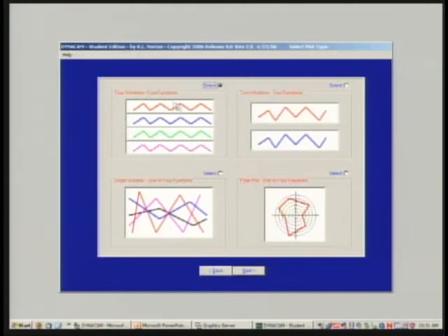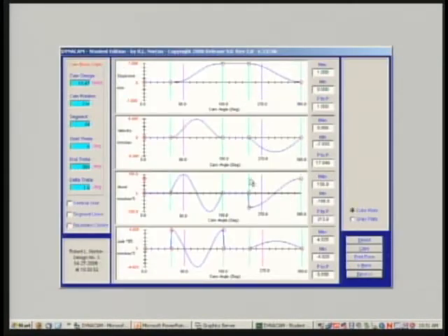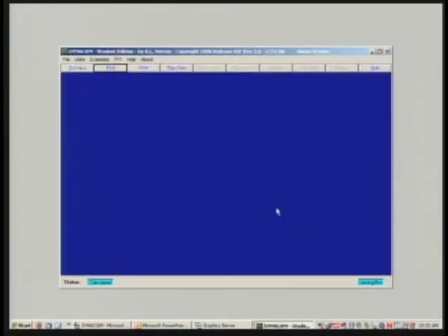If we go to the plot screens again, and I bring up this 4-plot business, now look at the acceleration here. Now there are 2 circles showing. That's a flag. The other circle didn't get drawn because it's actually over here. You can see them over here. This is the same point as this, right? 0 degrees and 360 are the same point. This is a red flag that something's wrong with your design. Acceptable in the jerk, but not in any of the lower derivatives. So I would reject this design and go back and change it to something else.